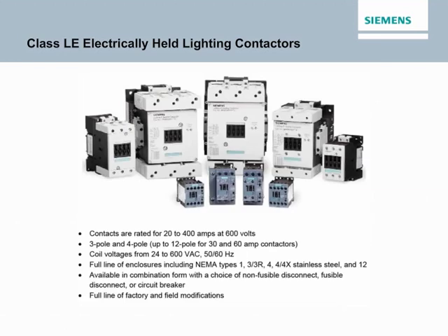Siemens Class LE electrically held lighting contactors are an economical offering with a compact, lightweight design. They are rated for tungsten lighting, incandescent filament, and ballast lighting, fluorescent, HID, metal halide, mercury vapor, quartz halogen, and sodium lamp, as well as for resistive and general use loads.